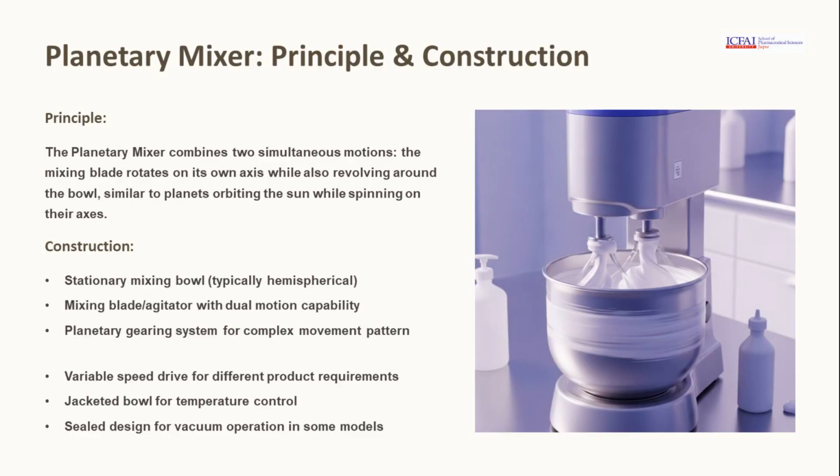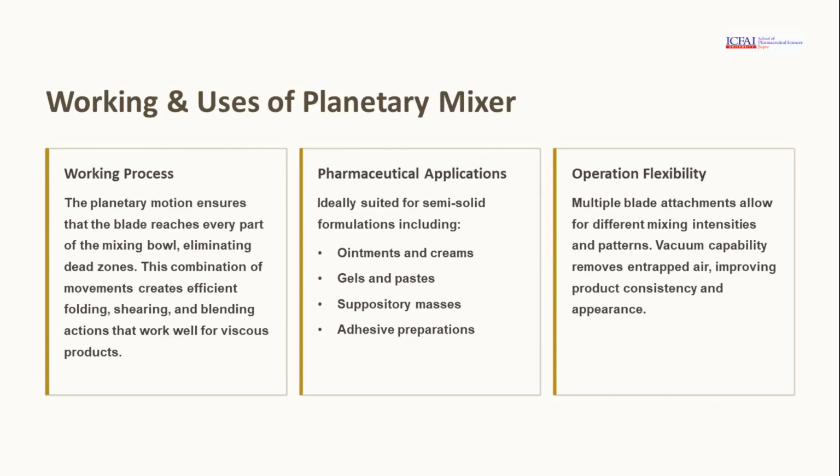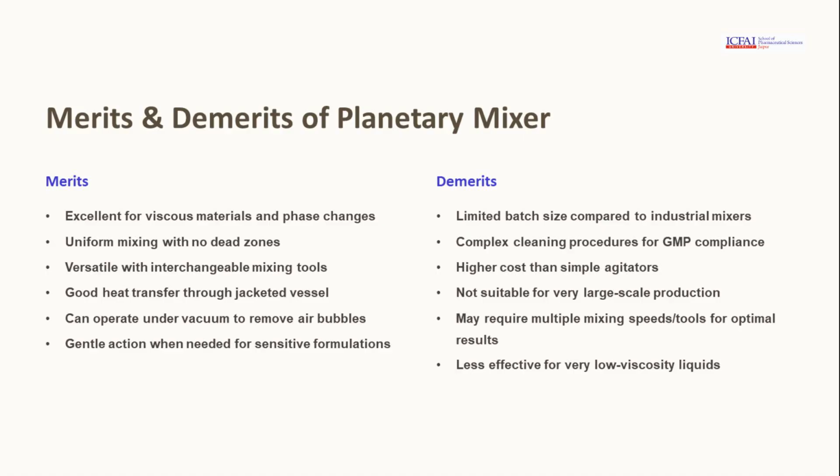The planetary mixer combines two motions for efficient mixing, with a stationary bowl and a rotating blade for complex movement patterns. Planetary mixers are ideal for semi-solid formulations, offering flexibility with multiple blade attachments for various mixing intensities. Planetary mixers are excellent for viscous materials but have limited batch size and are less effective for low viscosity liquids.